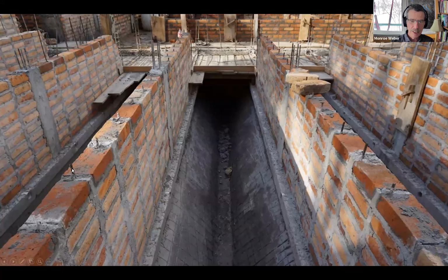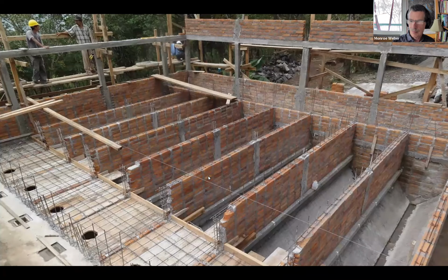And you can see the rebars here. There's rebar that goes right down through between the bricks. So in the mortar, in both directions, both horizontally and vertically, there are rebars embedded, and that's what makes this a reinforced masonry wall. There also are beams. Sorry, I should know my structures better than that. There are columns, and you can see columns here. These are poured concrete columns in the middle of the wall.